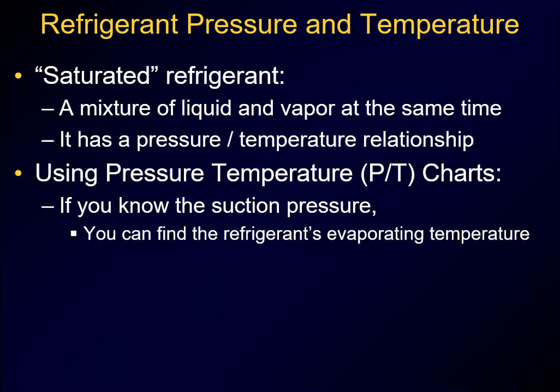How warm is it in the house? How hot is it outside? All of those things are going to factor in to tell you what your pressures should be. But I don't know what refrigerant you have, so without knowing what refrigerant you have, there's no way to know what pressures you should have.